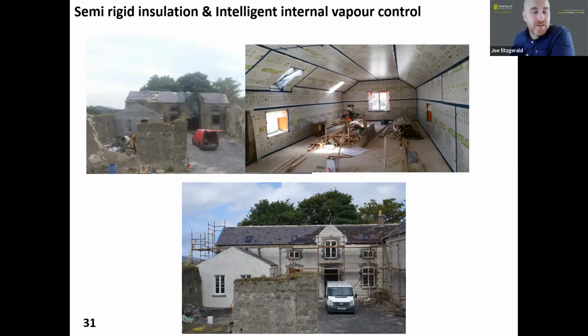So if you're going to opt for a stud dry line, it's important that the outside of the building has a protective render on it. So you might be asking, well, what's the importance of the vapor control layer if it causes all that sort of issues?